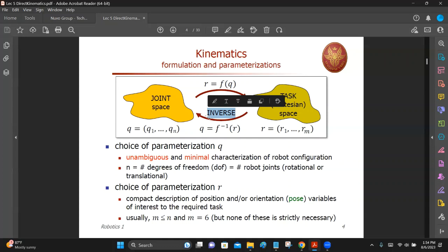At any later time, if you want the robot to go to point 1, all the controller does is record the joint angles, right? And then drives the angles to what you have previously recorded. So then naturally the end effector will be positioned at that point 1. Second, third, fourth, all of the points the controller remembers like that.